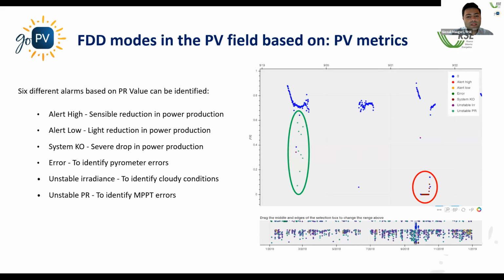So in green, you can see here an unstable condition that in general does not activate any specific system alarm, but gives an indication, a warning, let's say, while in red, there is an alarm that is activated due to a system fault or a PV string fault. So it automatically allows the technician to be advised about the specific faulty condition.